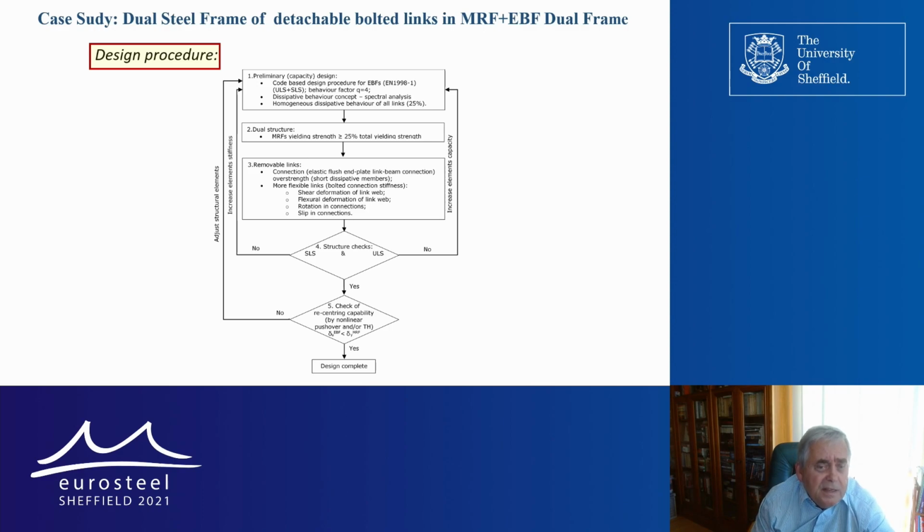We have this problem to ensure that we will have the moment frame with a capacity of at least 25% in resisting horizontal loading, and we have to keep this in the elastic domain in order to have the possibility to recover the initial position after detaching the link.